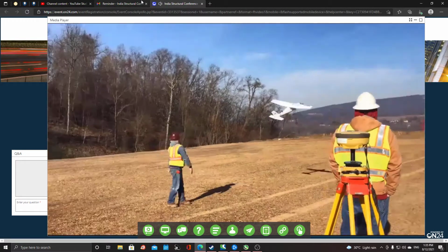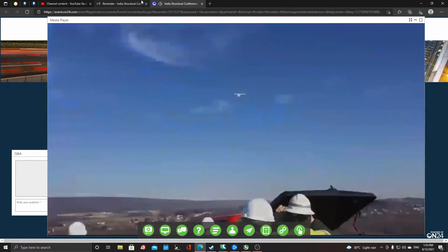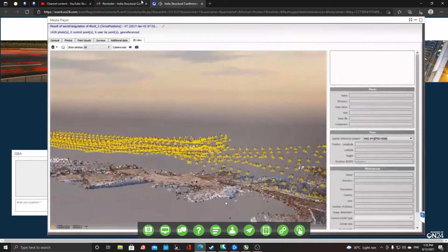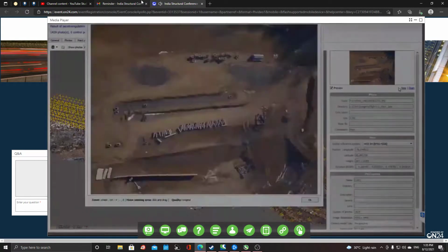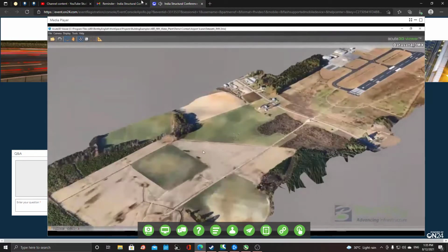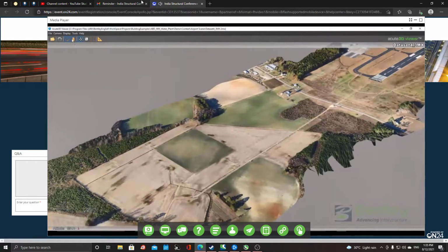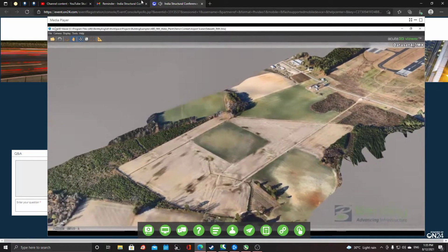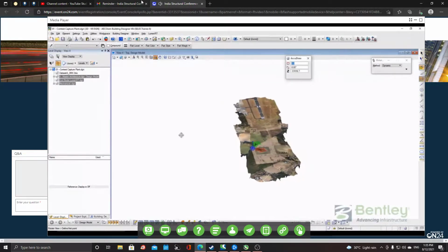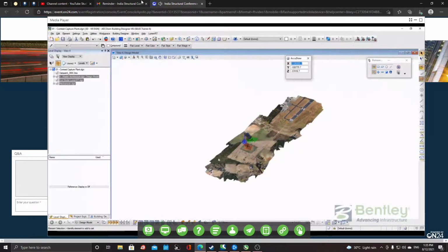Once these locations have been decided, the next phase is to capture the reality. With drone images captured, we can process these images inside Bentley ContextCapture, like these, to generate the 3D terrain of the site. Now these 3D terrains can be edited inside the CAD or the ContextCapture editor and can be consumed in any of the 3D modeling applications that we have or maybe third party.